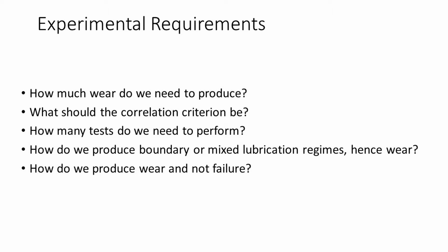A single wear measurement at the end of the test tells nothing about the wear rate or wear transitions. We therefore need to supplement post-test wear measurements with intelligent real-time observations, of which the most commonly used metric is to use changes in friction, electrical contact potential, and temperature close to the contact zone to indicate possible wear transitions. Hence, in many cases, we do not use real-time wear measurement, but use other methods to identify significant wear transitions.